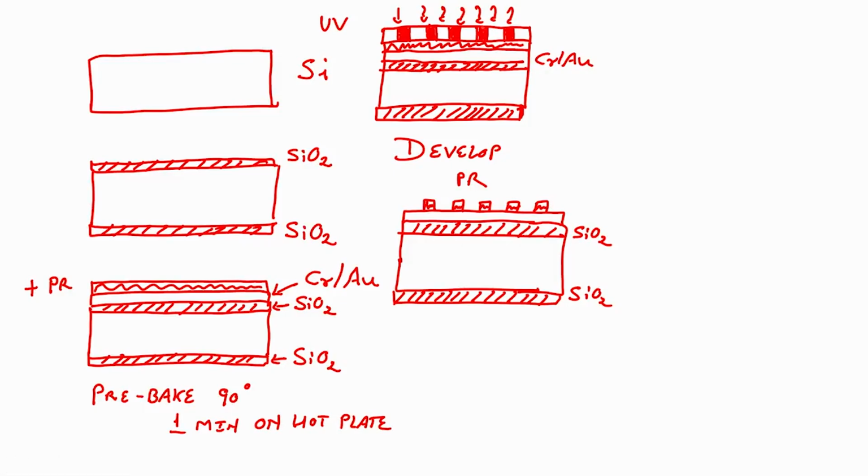Because I am using a bright field mask and I have used positive photoresist, I will retain the similar pattern that I had on the mask on the wafer, correct. So, now I have a positive photoresist on the areas which were not exposed to UV. All the bright area on the mask I can retain on the photoresist.